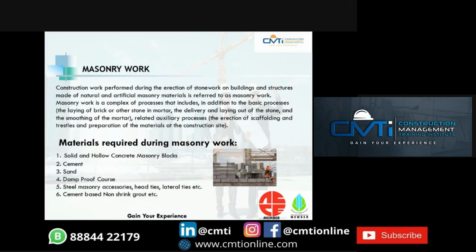Related auxiliary processes, the erection of scaffolding and trestles and preparation of the materials at the construction site, are also included in the masonry work. So what are the different materials required during masonry work? Solid and hollow concrete masonry blocks, cement, sand, damp-proof cores, steel masonry accessories, head ties, lateral ties, cement-based non-shrink grout, etc.